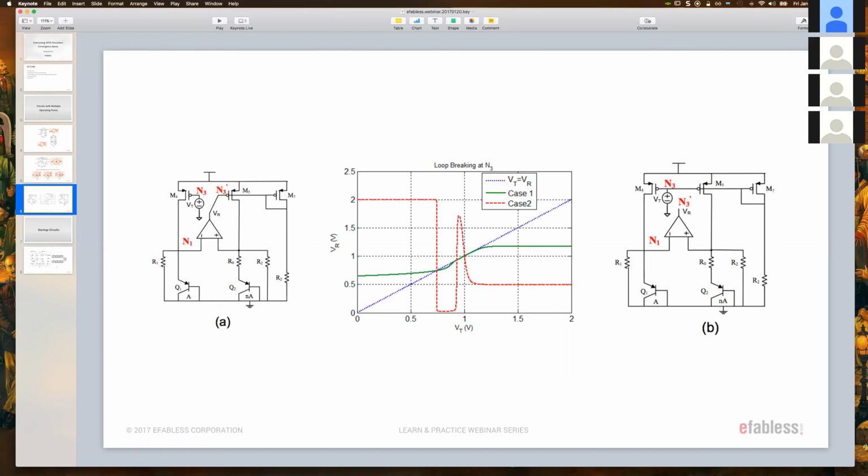And the second one is that the behavior of the circuit around the given operating point needs to be stable, or if it's not stable around a given operating point, it will get out of that state. But if it is stable, it's going to give you a bad solution, like for the reference value, giving you a lower valid point, and it gets stuck with it without a startup circuit.